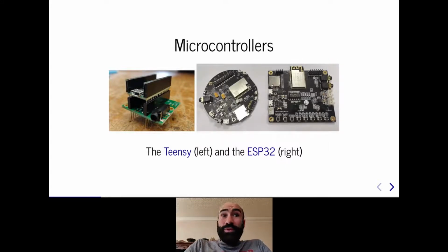Even more recently, new generations of microcontrollers, such as the ARM Cortex-M family or the ESP32, have been offering extended computational power, like 600 MHz for the Cortex-M7, suitable for real-time audio processing applications. Many of these microcontrollers also host a floating point unit, greatly simplifying the implementation of DSP algorithms.